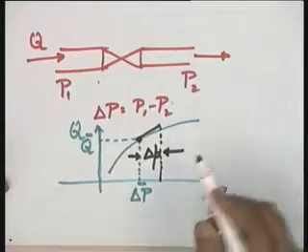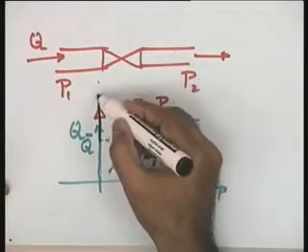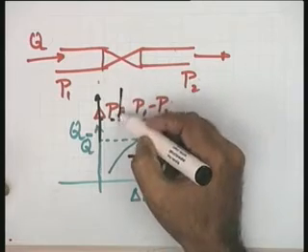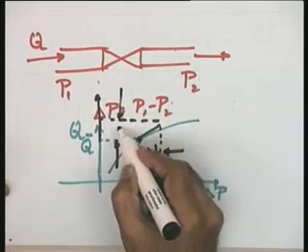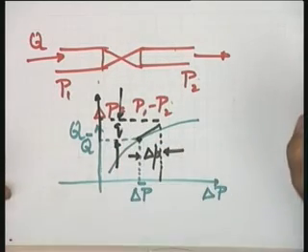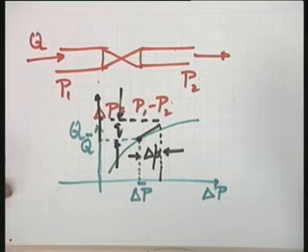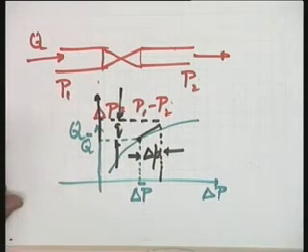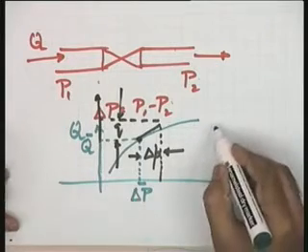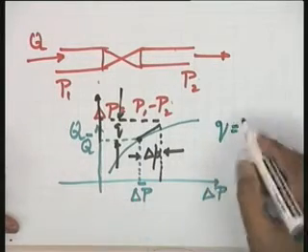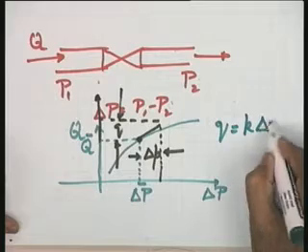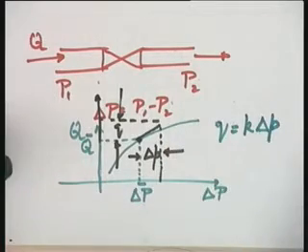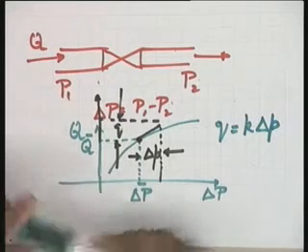So, del p is a small perturbation, and on this side let me say that this gives rise to a perturbation in flow, and let me call this q, small q, meaning thereby it is a perturbation variable. And it is obvious from this system that your q is going to be equal to some constant into del p, where the constant is the slope of this line.